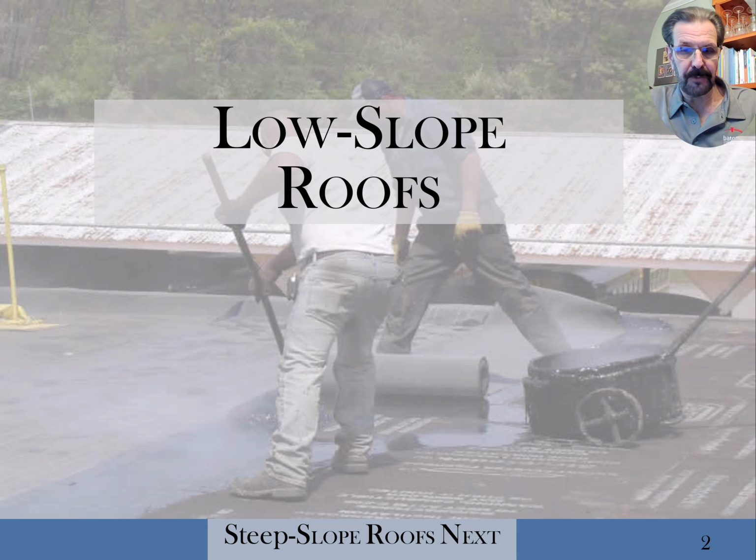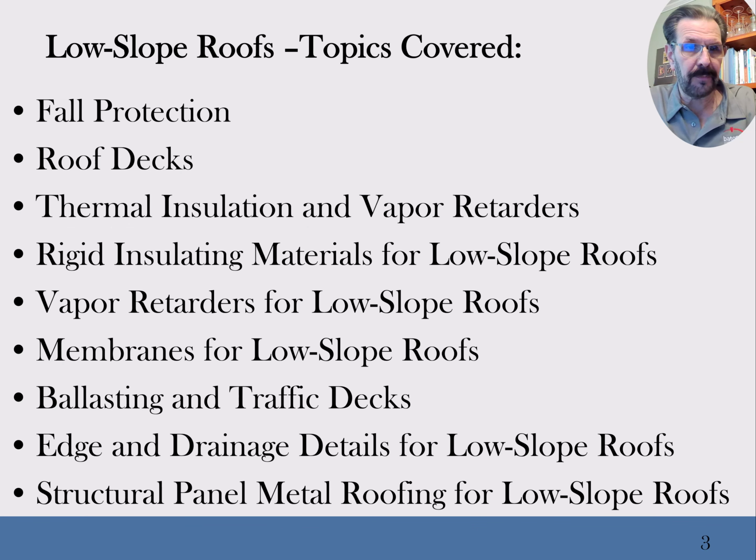But it deals basically with what we sometimes call a tar and gravel roof, but it's really not tar, it's asphalt. Hot asphalt mopped into layers of paper, roofing felt. So yeah, we'll deal with fall protection a little bit, roof decks themselves, the insulation and vapor retarders that we use, rigid insulation that is used on top of roofs sometimes, vapor retarders for low slope roofs in general, and various other membranes. And then there's ballasting.